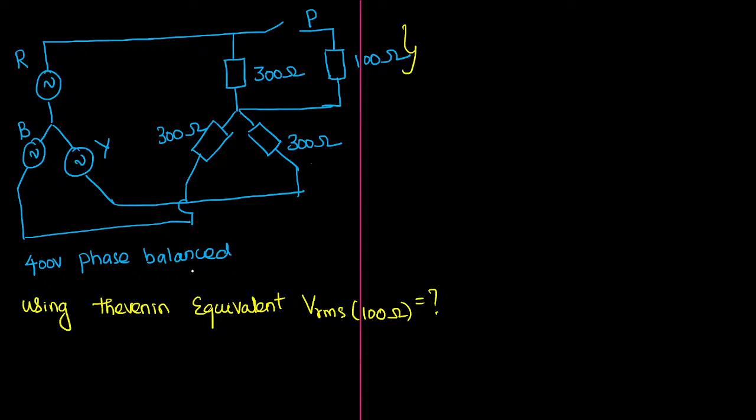That is the given circuit. You can see the supply is having 400 volts balanced. Remember one thing, always in case of a three-phase circuit, you will be dealing with the line to line RMS voltage only. By standard default, they will give you only line to line voltage, and that too is RMS voltage. Don't forget this. That is very important.